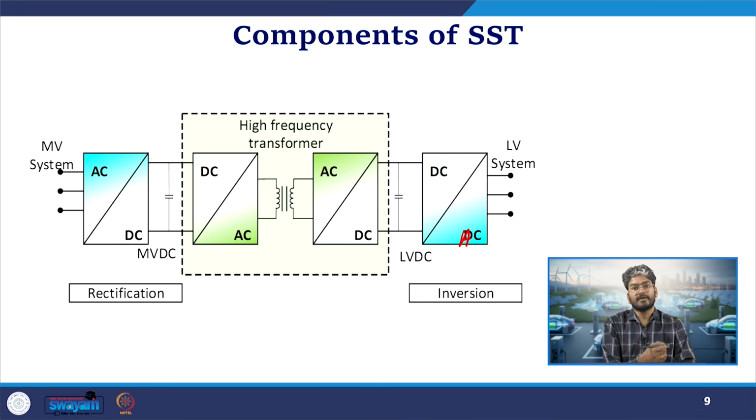In conventional power transformers, we generally have forced oil cooling, where the transformer core section and the windings are immersed inside the transformer oil, and they absorb the heat generated because of the loss in the transformer, and it goes to the outward fins, where forced air is injected on the fins, and they radiate the heat or the loss created inside the transformer core section to the outside atmosphere. Those cooling arrangements can be eliminated because the size will be very less, so it can be air cooled.